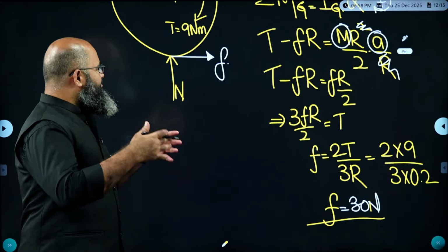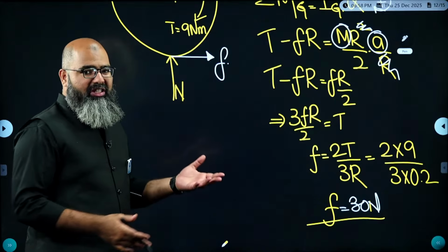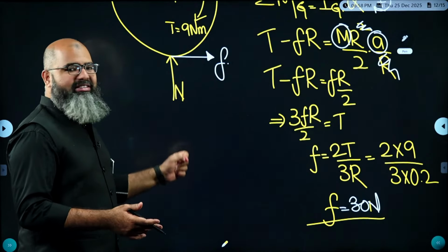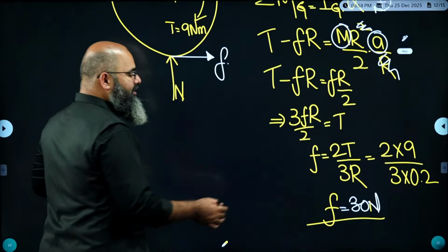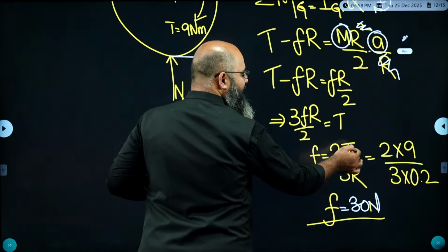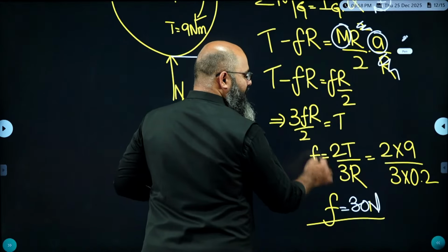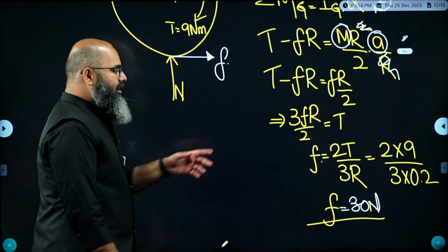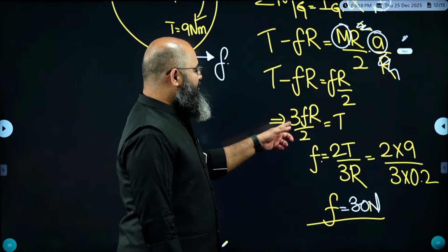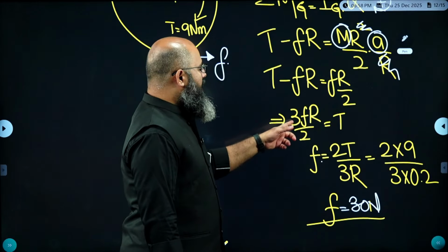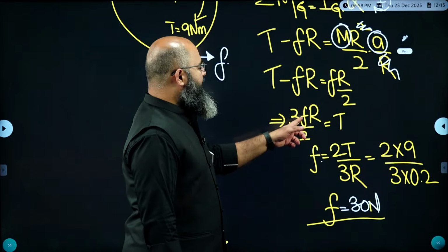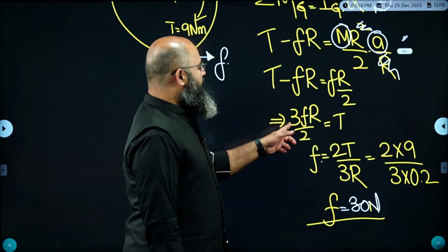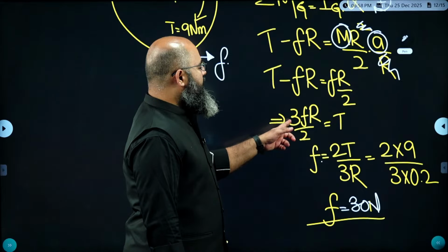Therefore, if I want to complicate this question, I can create one more question below this. I can say, what is the maximum torque allowed? Now for maximum torque allowed, this will become Fs and this will become T maximum. Fs is 70 over here. Accordingly, take 70 over here, so 7 times 3 is equal to 21.